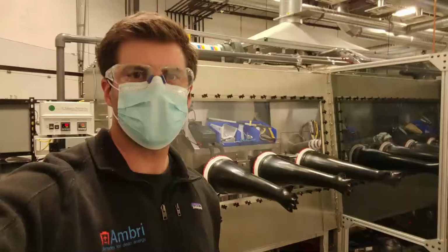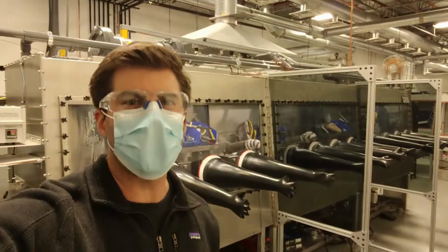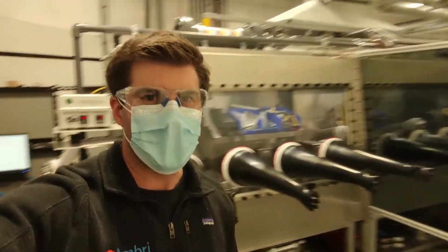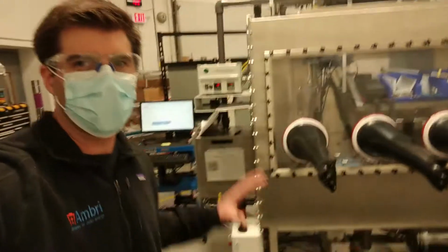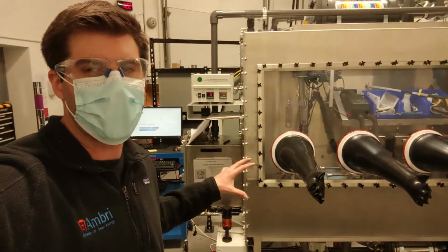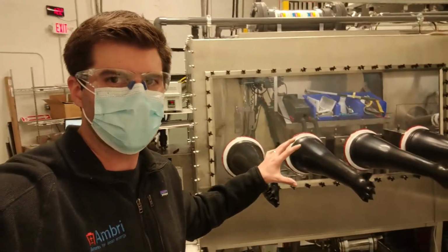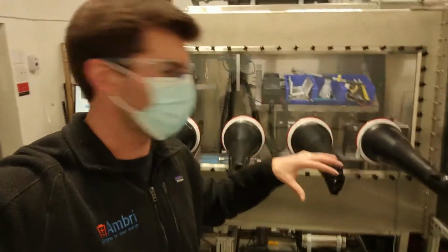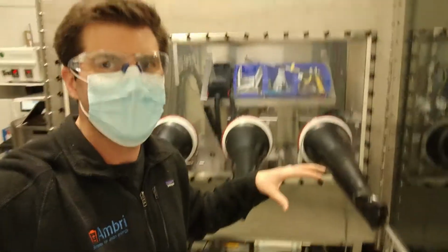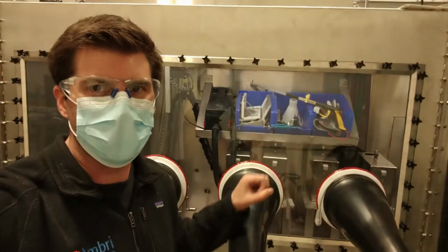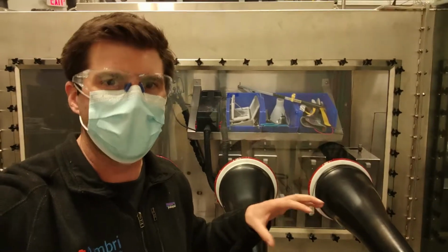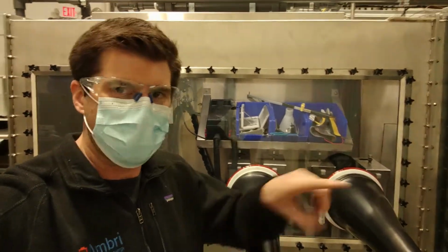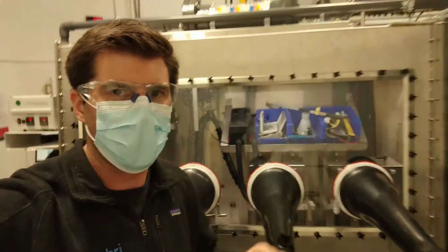So here's the front end of the cell assembly system. It's really quite a simple process. Cell components are loaded through the antechamber into this purge box system here. The calcium and antimony metals are loaded into the cells, and you can actually see some examples of cells here that have their calcium and antimony loaded into them, and the cap is welded on, which includes a pouring window.